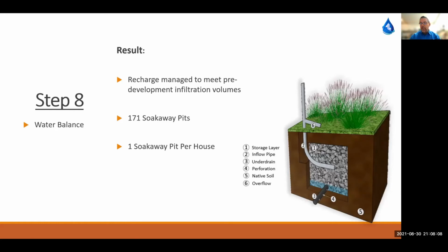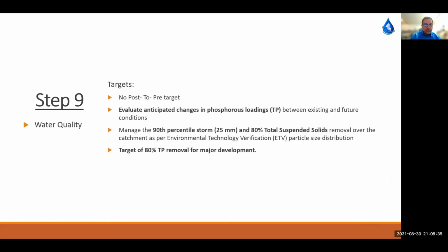This is one of the low impact development technologies, or LIDs, and it requires a specific design where we introduce porous substrates below the ground to enhance the storage. We also have to take a look at the native soils to make sure that the rate of infiltration is sufficient to get rid of that water between storm events.